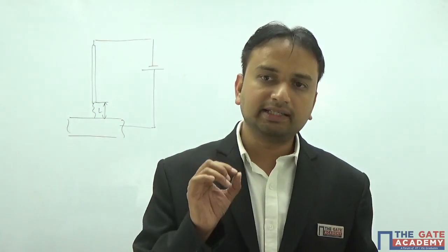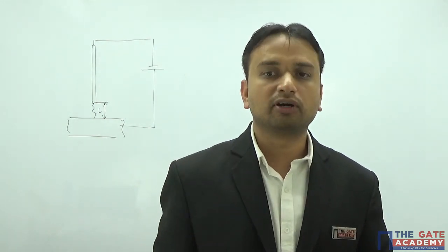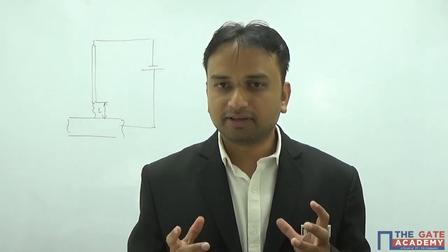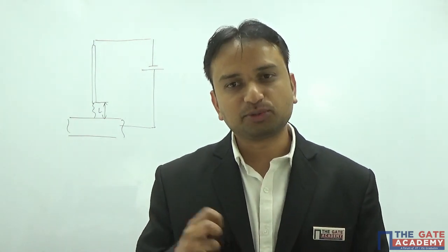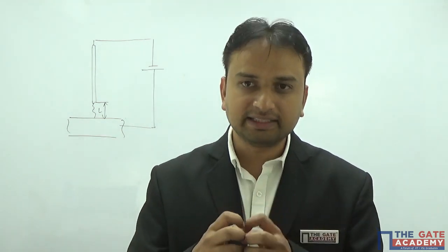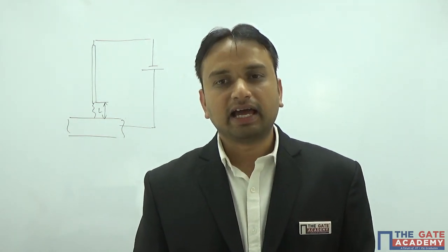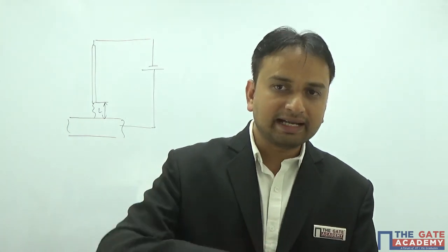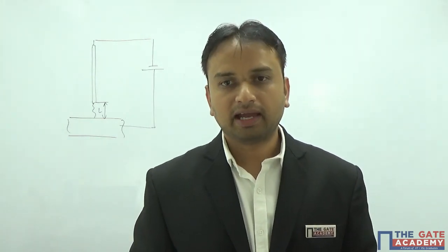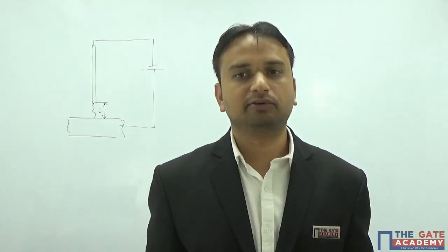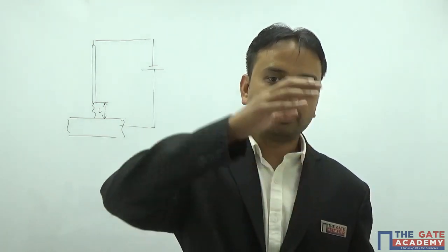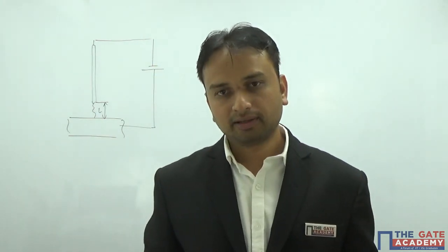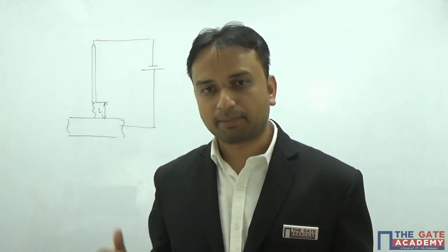Now, to eject an electron out of its orbit requires a huge amount of energy, right? If the potential difference is too high, this ionization will happen, and free electrons will be available in that particular air column. And when a sufficient amount of free electrons are present, these charges can travel from the clouds to the earth. Getting the point? The same thing is happening over here.